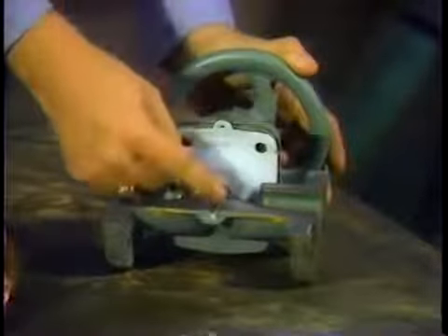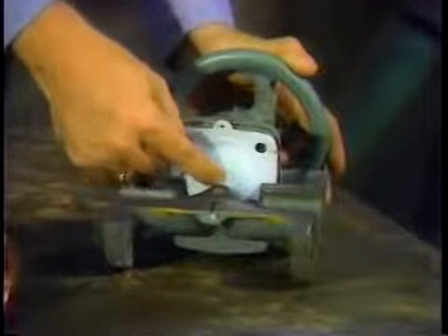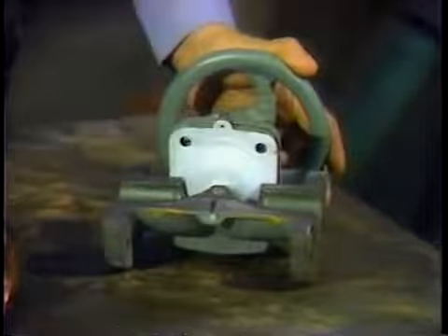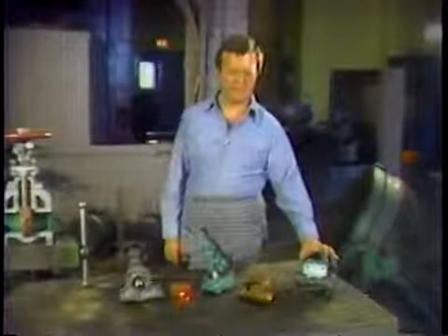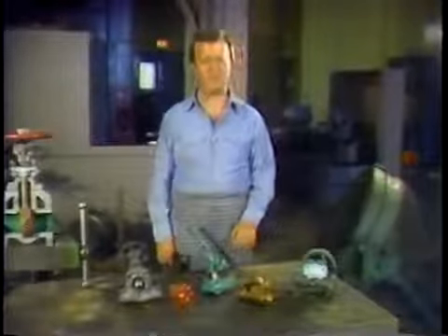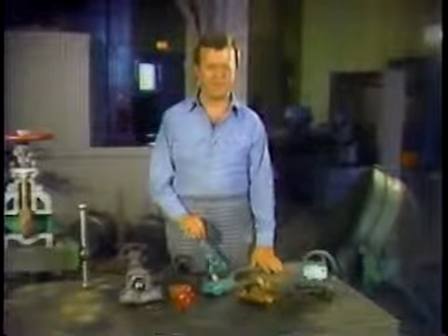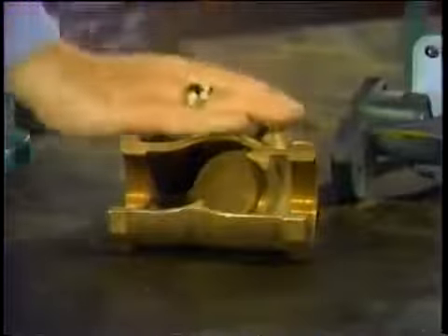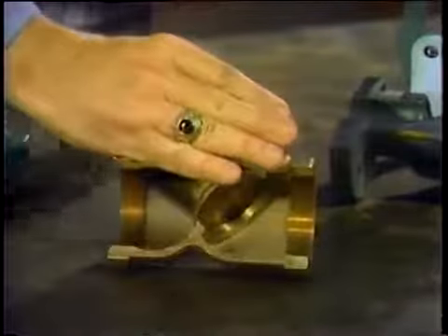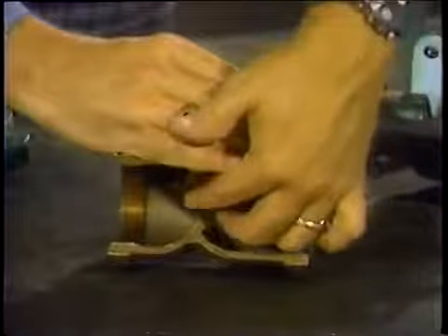to provide a seal that prevents leakage into other working parts of the valve. These valves are most often found in systems with a flow of chemical fluids or harmful gases, where any leakage could be potentially dangerous. Finally, we'll look at a check valve. These valves are used to allow the flow to go in one direction.